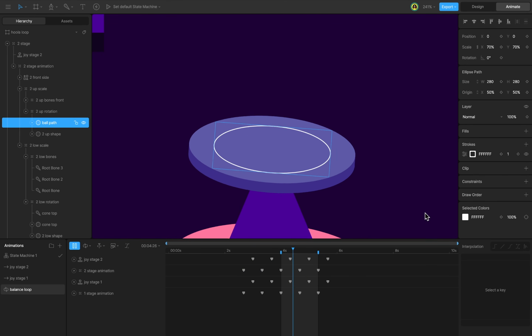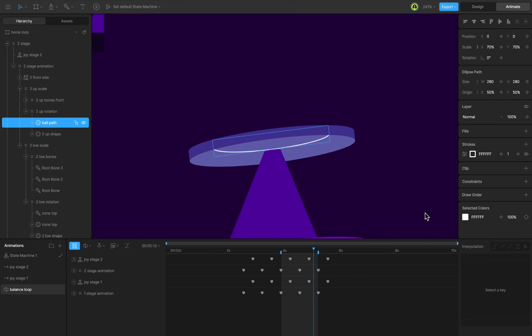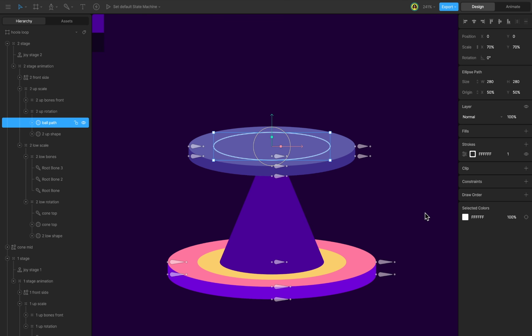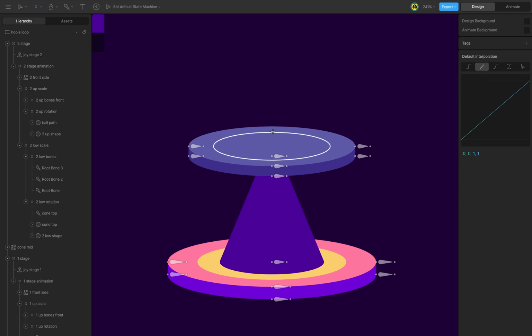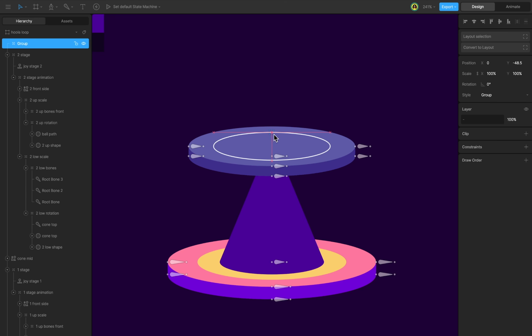We see that the created path follows the animation precisely, since it created the same plane. Press G and create a group. This group will serve as a tracker for path motion. Select Bolt Track and add a follow path constraint.